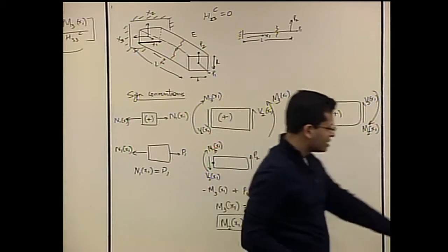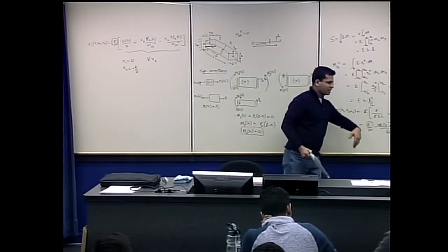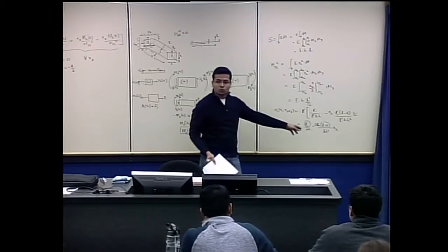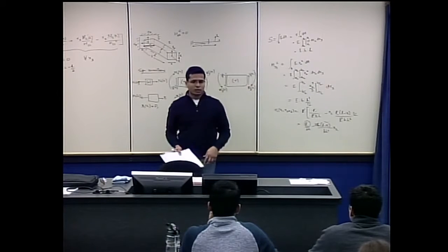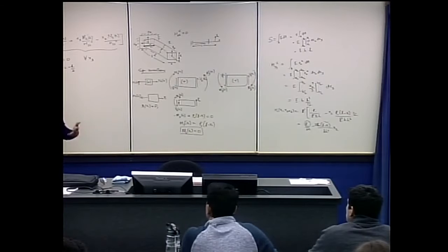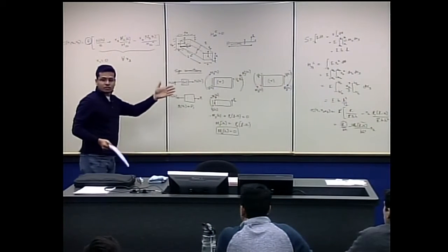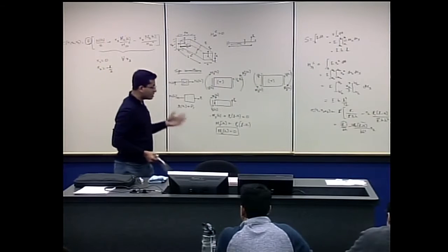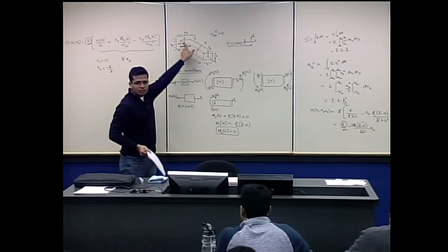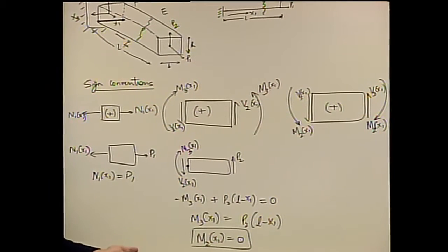So we will just try to maximize this term then, and when we maximize this term, it is maximized at both h over 2 and minus h over 2 for x2, right? One would be a positive stress, one would be a negative stress, but they both would be maximum. So there would be two locations, two edges for maximum stresses, but because there is an axial stress, there is no longer a maximum stress on the top edge, it's only at the bottom edge.